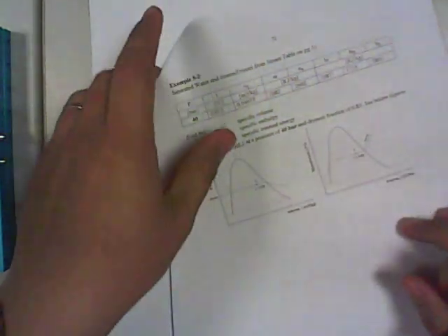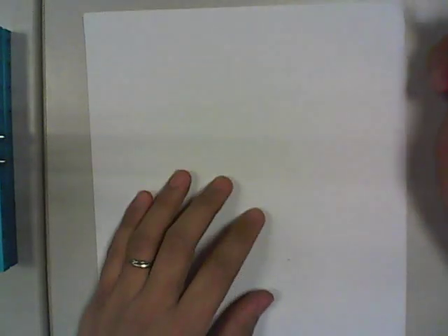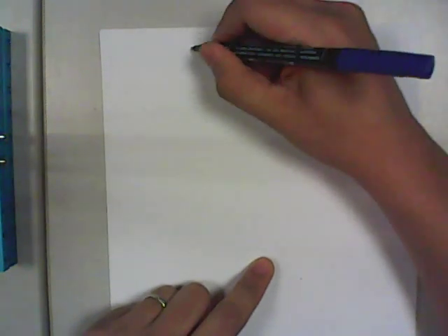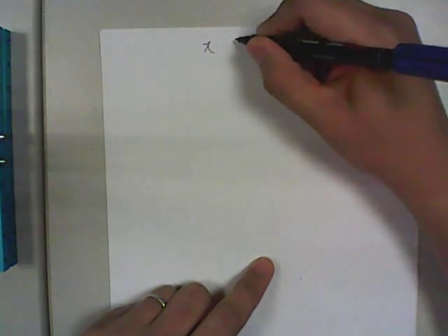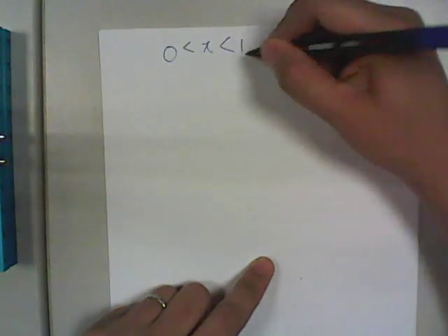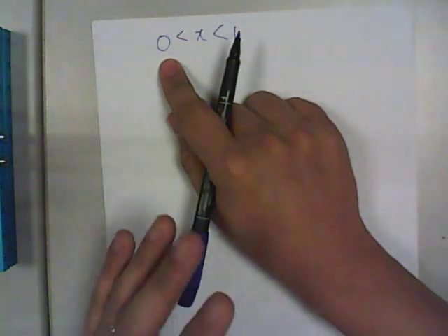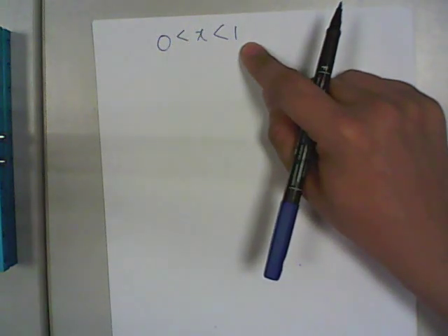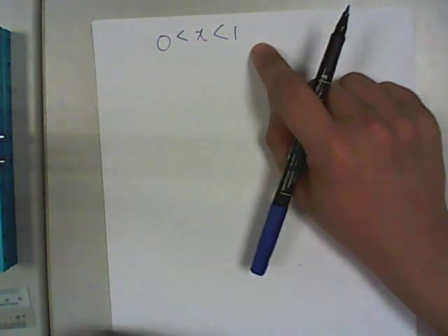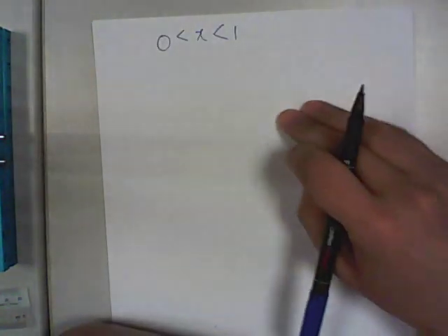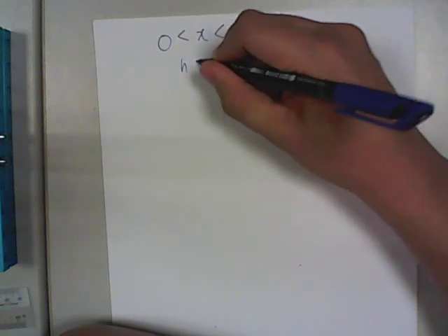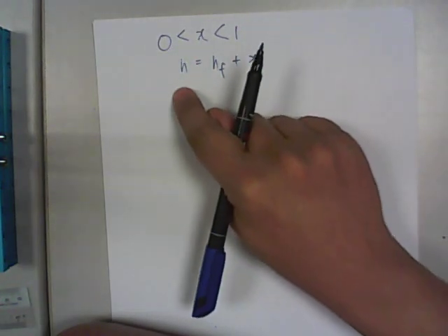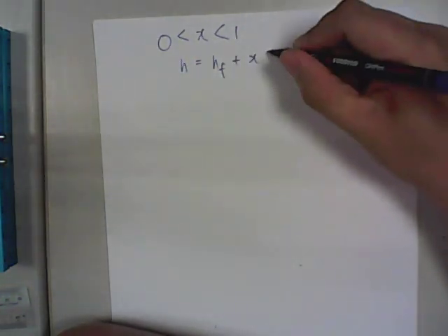Hi, so previously we left off talking about the dryness fraction equations. To revise, it comes in the form of the dryness fraction x, where x is between 0 and 1. 0 being totally wet, along the F line, and 1 being totally dry, along the G line. If it is wet steam anywhere under the hill, your enthalpy will have this formula. You'll be able to obtain the enthalpy at that point based on the dryness fraction and both end values, F and G.